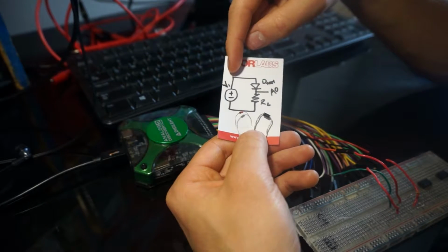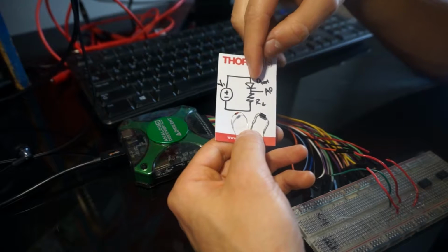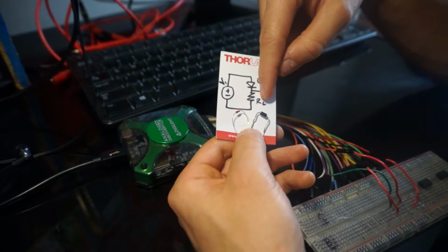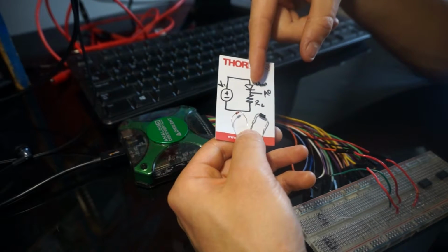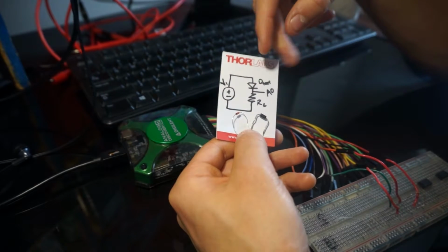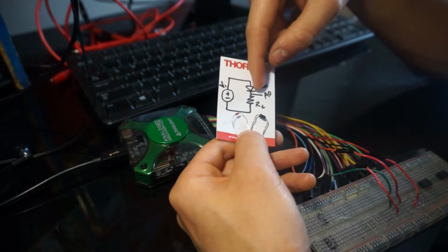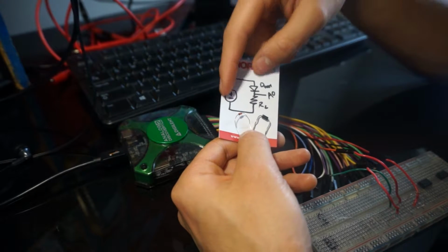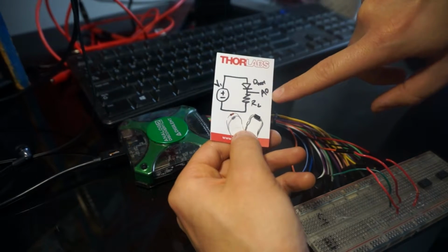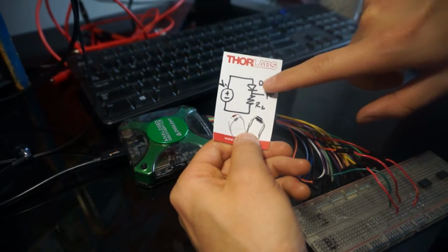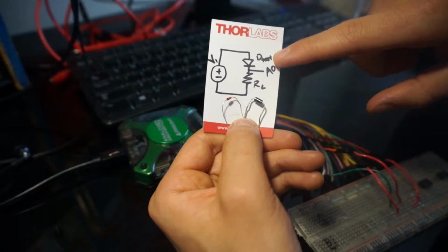All we're going to do is put one of the Analog Discovery's voltage outputs in series with the diode and resistor, and what we need is the voltage across the diode and the current through this loop. And so the voltage across is easy. We're just going to say it's the voltage that we think we're supplying. We're going to tell the Analog Discovery to supply a certain amount of voltage, and we're going to subtract that from the measurement point between the diode and the resistor, and that'll be the voltage across the diode.